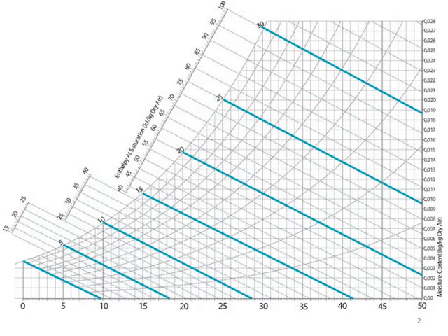Let us begin from the axis at the bottom, wherein you can see a graduated scale from 0 to 50. Each main division is 5, 10, 15 like that, and again it is subdivided into 5 equal parts. This is nothing but the dry bulb temperature. So it increases from left to right.